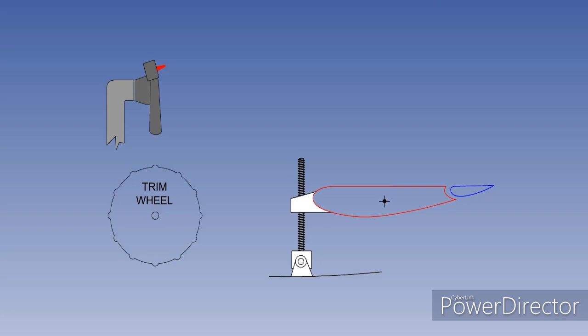When the early jet transport aircraft were being designed in the 1950s, it was found that an elevator trim tab did not provide enough pitch trim authority for the increased speed range and CG range required. So an alternative method of pitch trim had to be used: the variable incidence trimming tailplane. The variable incidence trimming tailplane is still in use on today's jet transport aircraft.